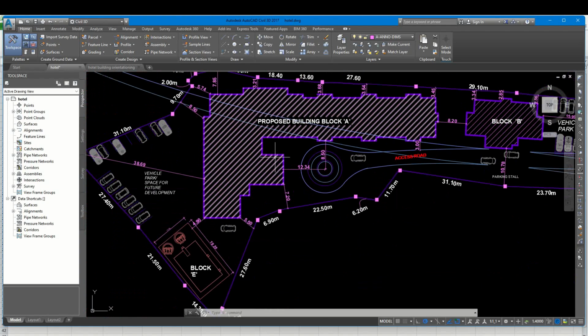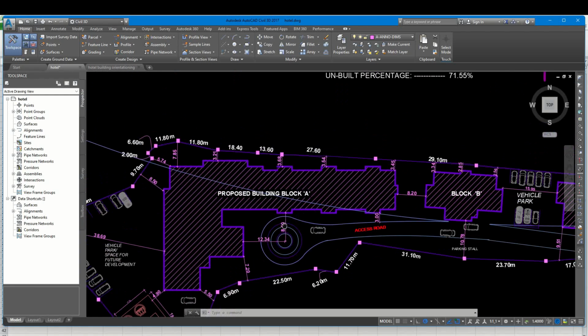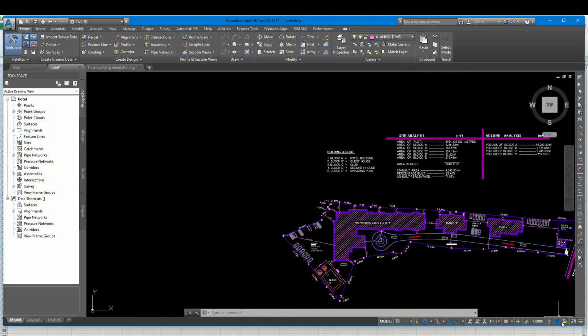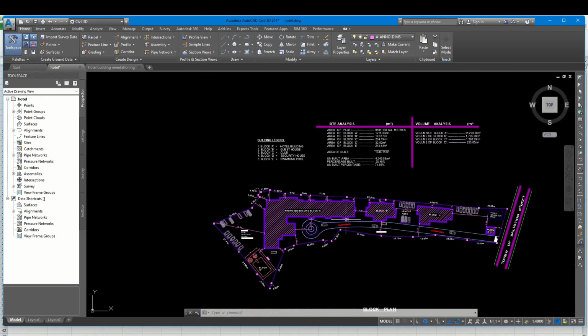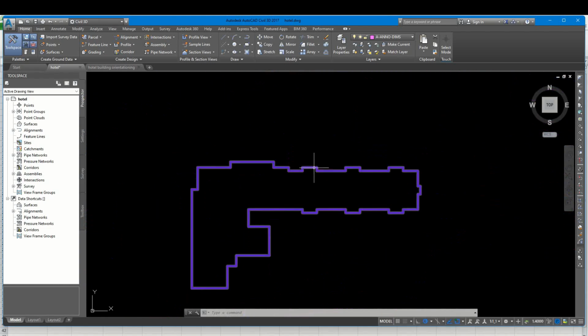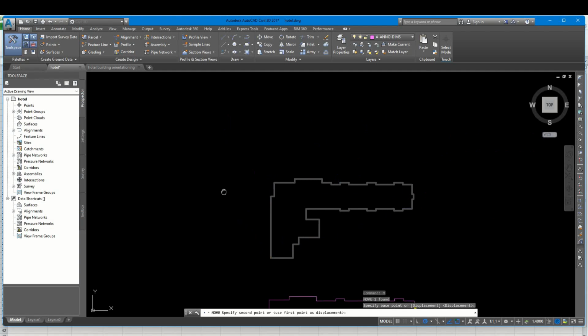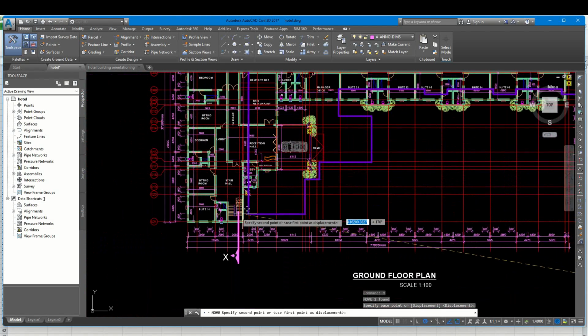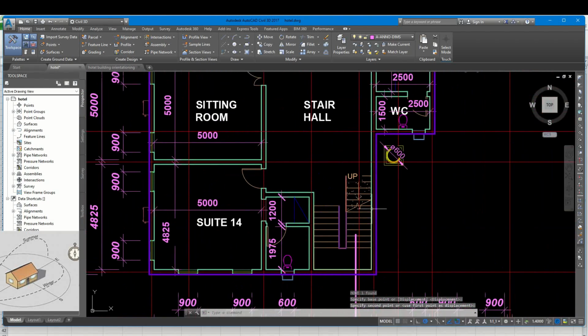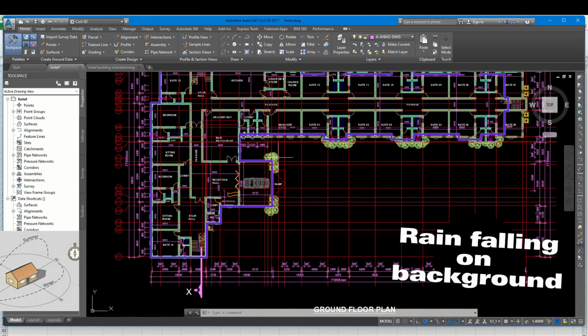Okay, to check if the measurement matches what you have received from the surveyor, first, pick all this line for the hotel blocks and make it a single entity, just as I did, and move it from a base point here to the original building block that he has given to us as the architectural drawing. So the same orientation, and I found that yes, the width is okay, and it's okay from here going to this point. Going to this point, I now see that there's a shift.